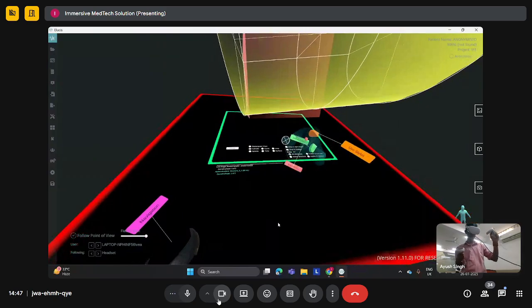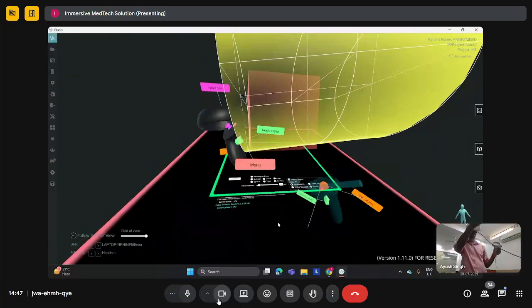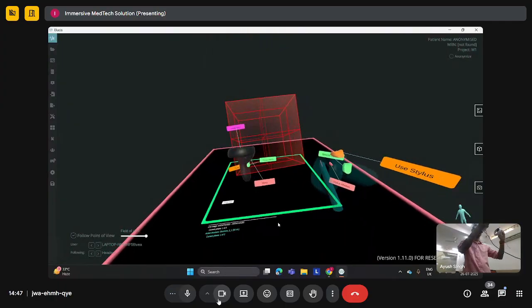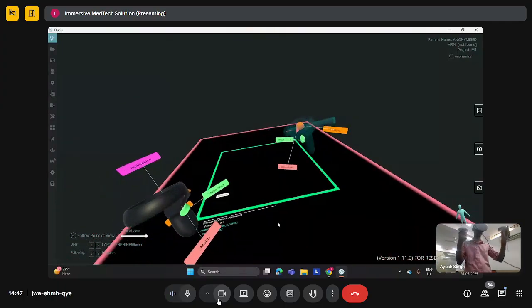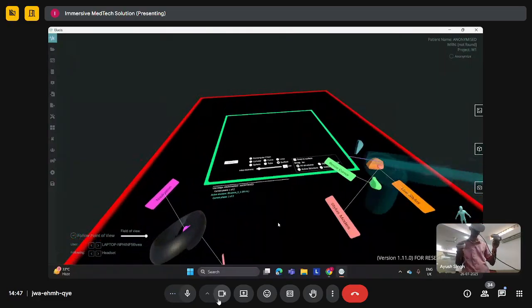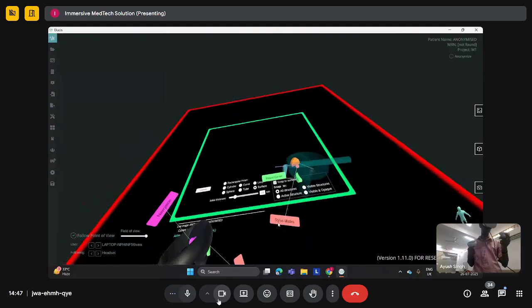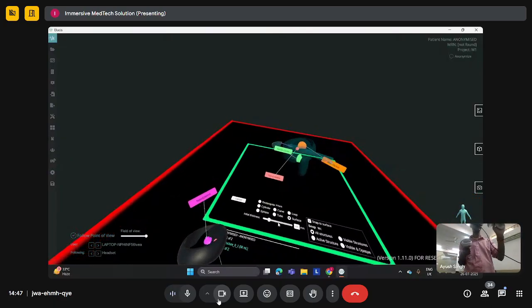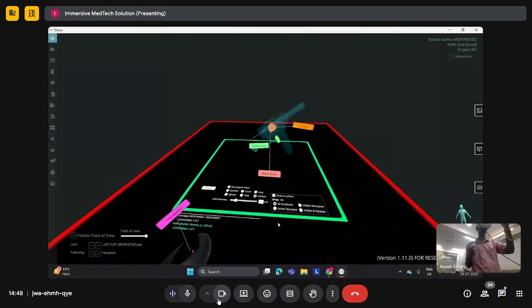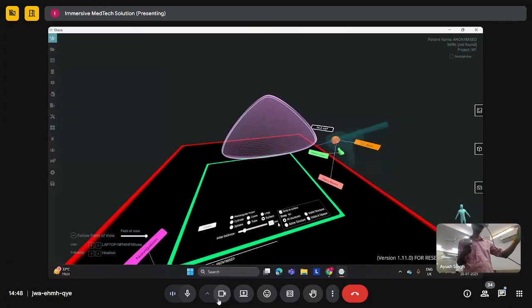Because this was the particular surface that we had, now let me take a completely new surface. I'll just remove this particular part and delete it. I'll use create. Now, taking a rough surface, I can set the initial thickness and final thickness to whatever I require. Whenever I am creating a surface, this is my trigger button that I use to create the surface's initial point. For example, I am creating a surface.